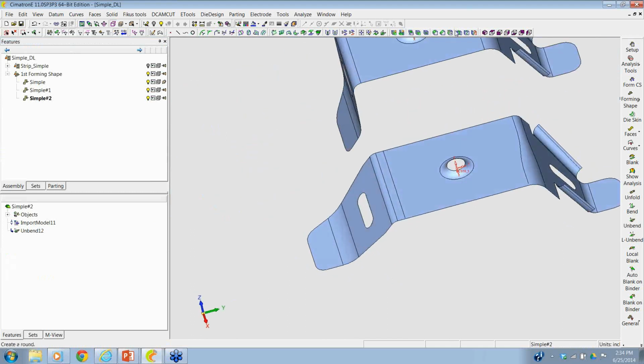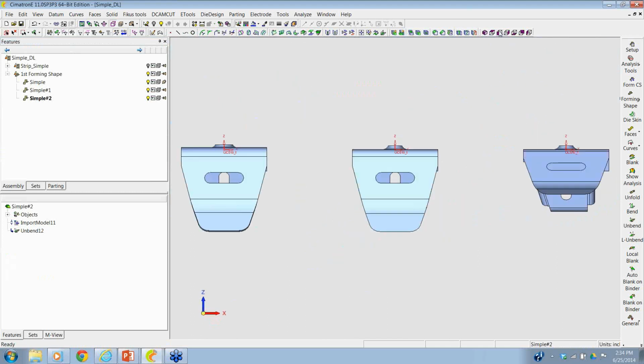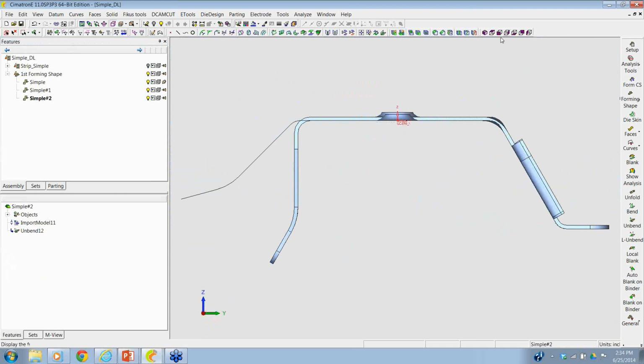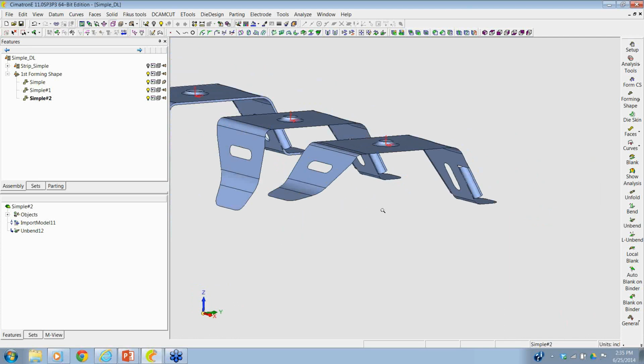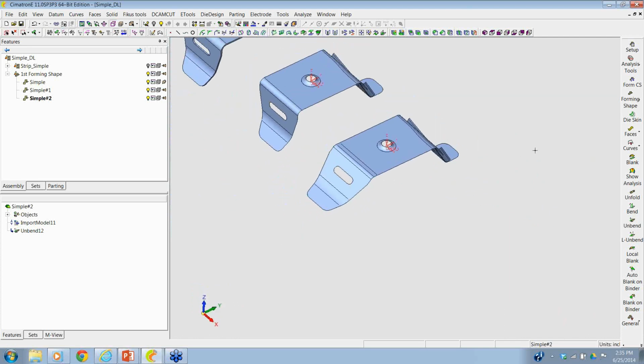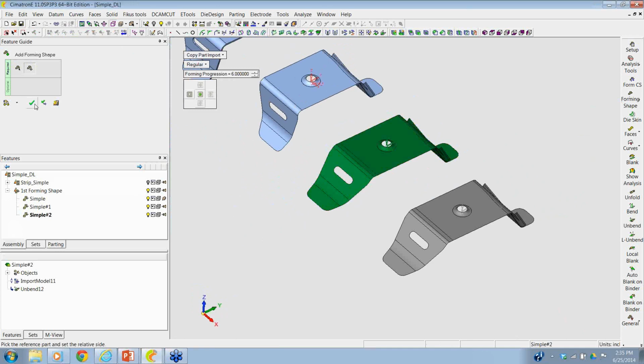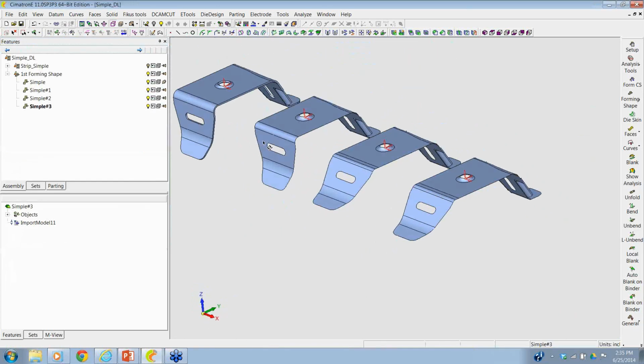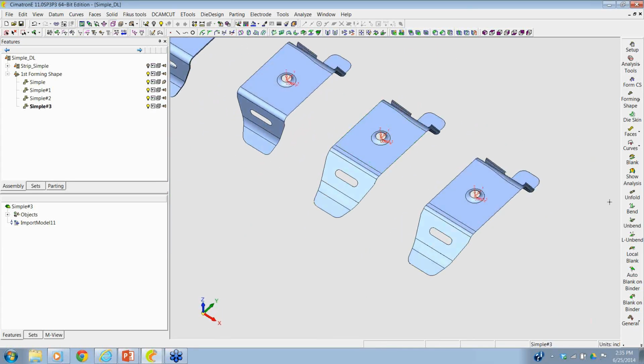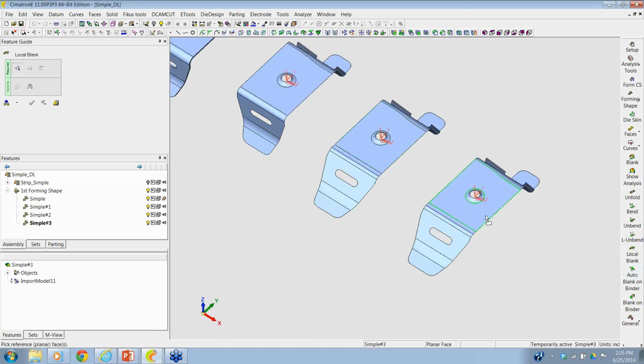And if I put this in a side view, the other side view, here you can see how it's kicked away. Now when I come back to do my finish form, I'm going to be pushing down on this and forcing it into that die form to capture that. So that's one way I've seen done quite a bit to deal with spring back, that second hit, and changing the radius. Let's go ahead and make these go to a flat now.